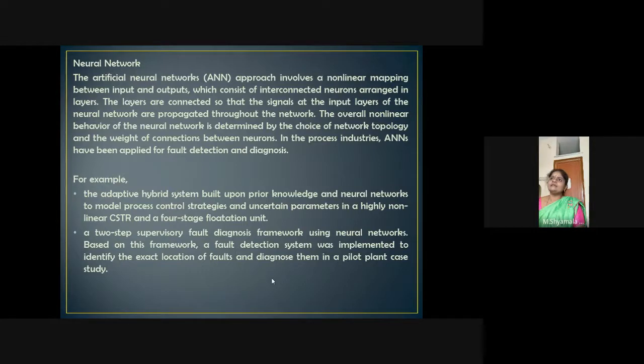So in that I have identified the nonlinearities which are present in the entire process in a CSTR, and how the states which I have estimated, internal states, and the output can be controlled, output can be achieved as desired by controlling the internal state parameters.